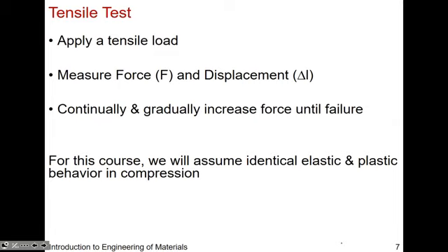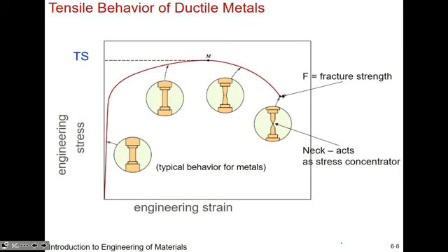Okay. Well, we've already talked about this in terms of measuring the force and the displacement. So let's go to that. Here is pictorially what's happening. You start with a dog bone, and the way you design your material, you cut into this dog bone so that you can actually clamp your instrument to your material and induce the failure where you want it to happen, which is this middle section here. So if you design the dog bone in this way, the fracture will always happen in that region.